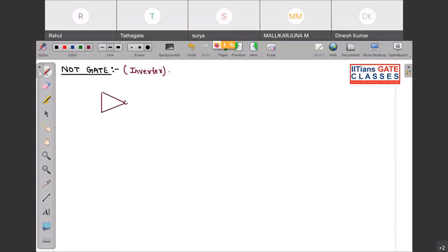is something like this. See, I will be dealing a very important concept after this. So if this is A and this is X, so logical expression is A bar. Now what do we mean by bar? This bar corresponds to complement. Okay, if I want to draw the truth table, the universal truth table, so basically A and this will be X. So if A is low or A is high, so output will be just complement.